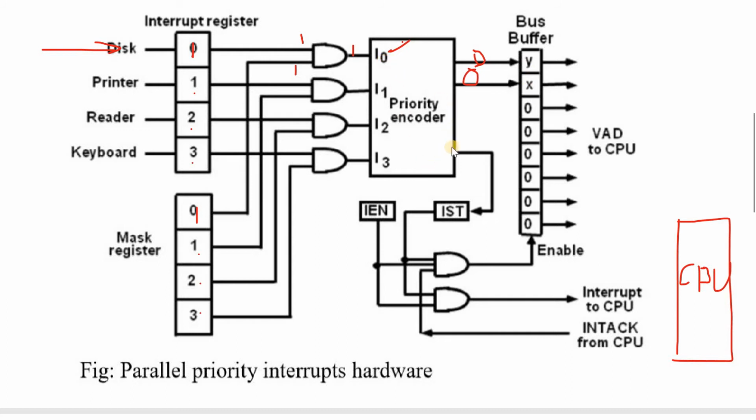In the second case, if the interrupt request is generated, the xy values go to 0 0, and at that time the interrupt status flip-flop is enabled equal to 1. When the interrupt status is 1, the interrupt enable automatically goes to 1. If the interrupt status bit goes to 0, the interrupt enable goes to 0. If it is 1, this value automatically holds logic 1.